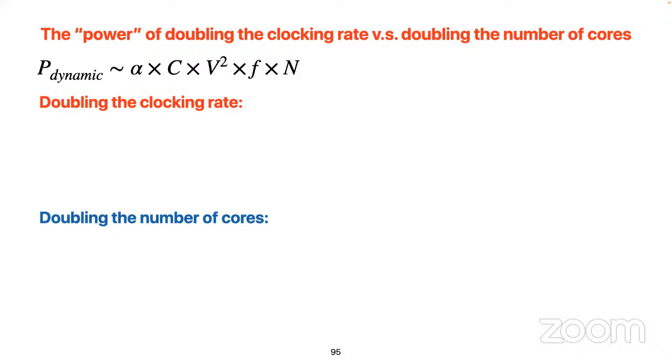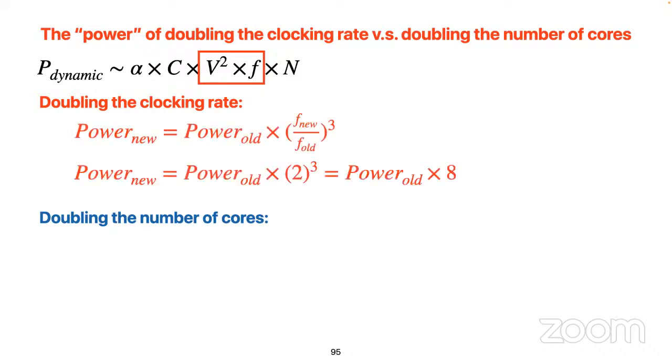However, even with simultaneous multi-threading, it's still a single processor with a single wide-issue pipeline. So if you want to speed up the execution of that kind of processor, the only way is to make your frequency higher or make your microarchitectural design better. But according to our theory, if you double the frequency, you are going to see a cubic relationship with the frequency you increase. So you might get 8 times the power consumption of your baseline design.